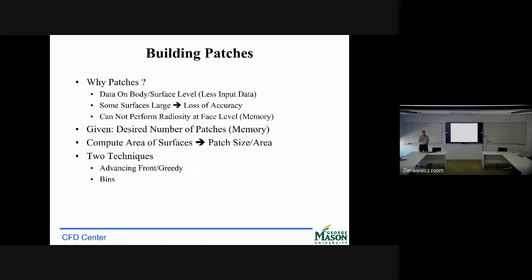Okay, why would you need patches? Well, think of a million triangles. In the worst case scenario, the radiosity matrix is full, so you have 10 to the 12 real numbers there. For the calculation of thermal comfort from one building to another, or for a person walking between these two buildings, whether you take the super fine faces or something a little bit coarser, the result is not going to be very different. But you will be able to do it, because if you really want to do it with 10 to the 12 storage locations, it's going to be expensive.